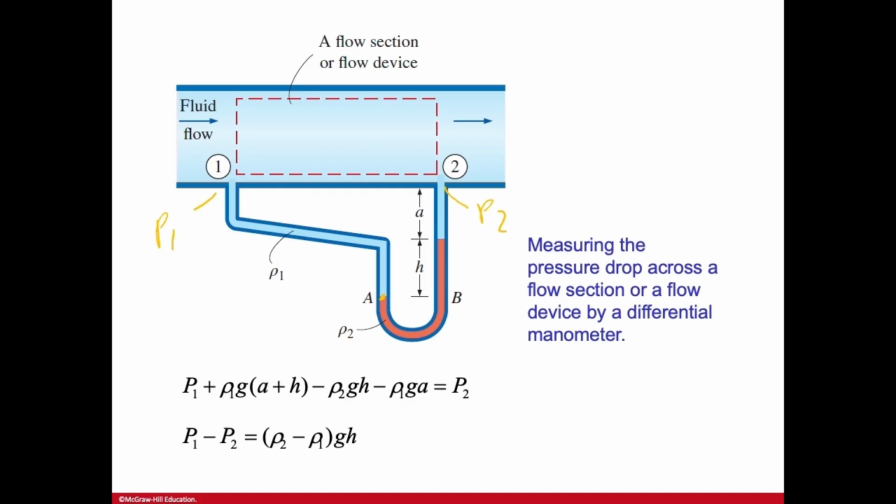Pascal's law states that it has to be the same fluid across which it can be applied. So you cannot say something about P1 directly with respect to this, because it's two different liquids. If you say point B and 1 directly, you cannot relate them because there are two different liquids there. So it's better to take it step by step, or that's what I would suggest. So let's go through the steps.